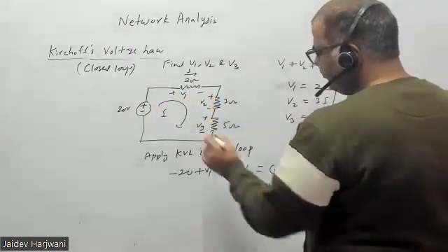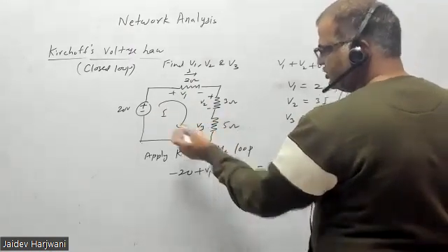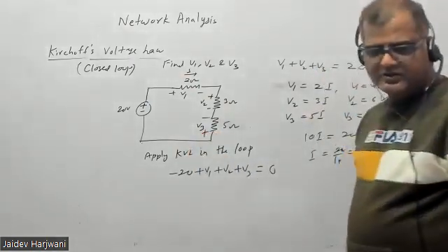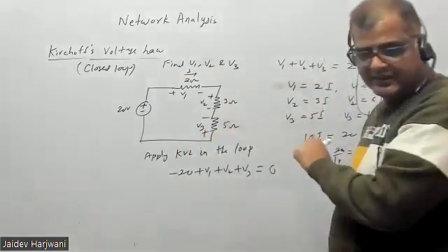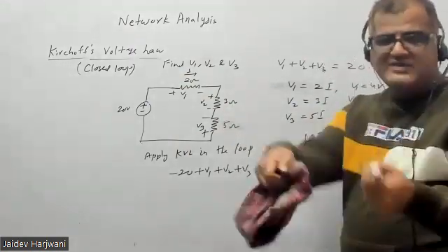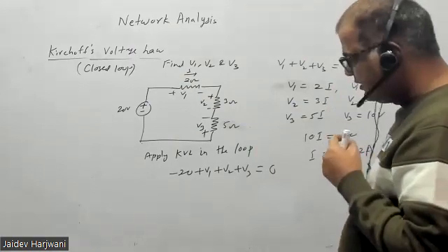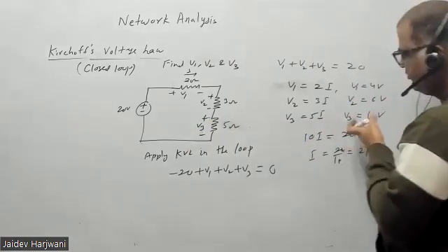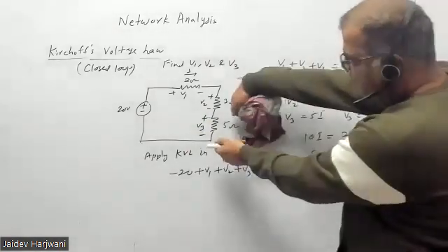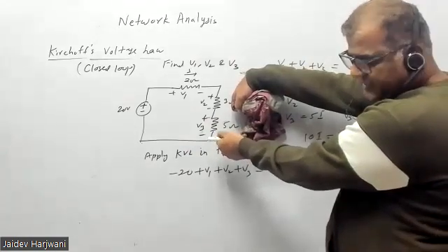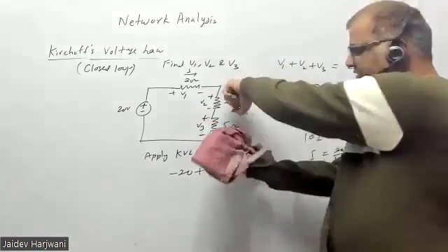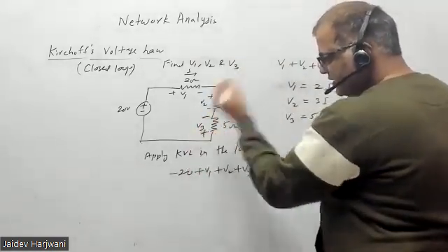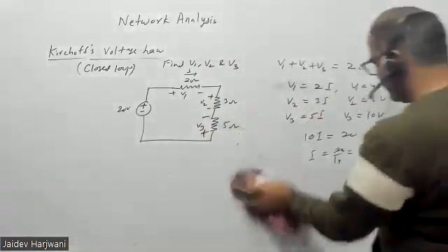Now let me put this sign opposite. If current is flowing like this, say now this is minus, this is plus. When I put the sign, that doesn't mean this is the actual sign; this is how I am measuring. If I measure V3 minus V1, that comes positive, 10 volts, with the voltmeter having the same polarity in the direction. Now if I measure with the voltmeter opposite, like this, tell me what is V3 now? How much will V3 come?